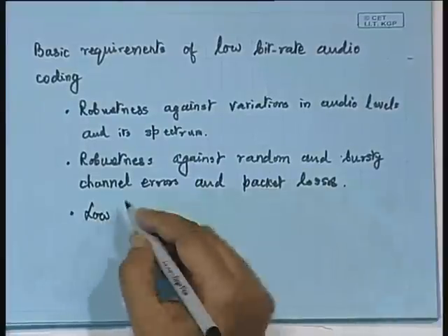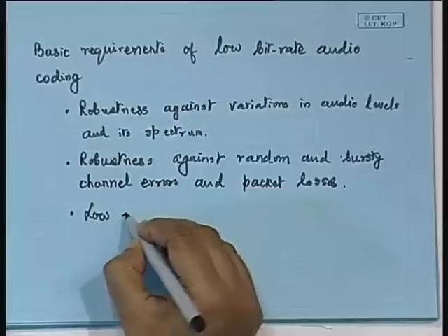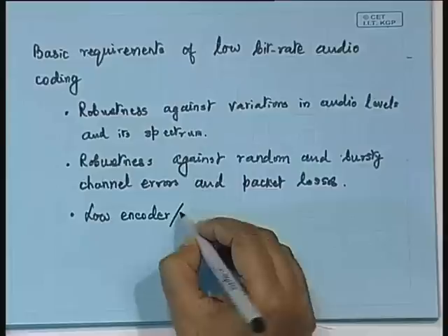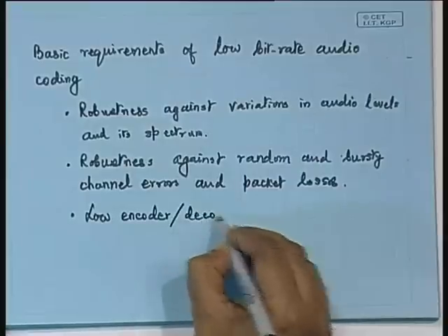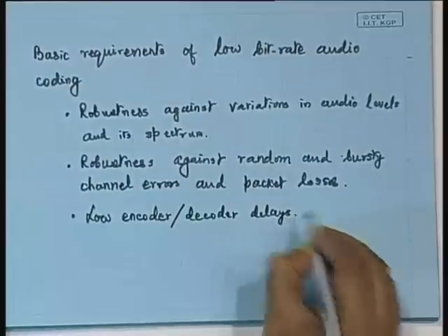It is really very difficult to see. So, that is why the basic requirement of low bit rate audio coding should be that it should have as minimum encoder and decoder delays as possible. So, low encoder and decoder delays, this is another requirement.